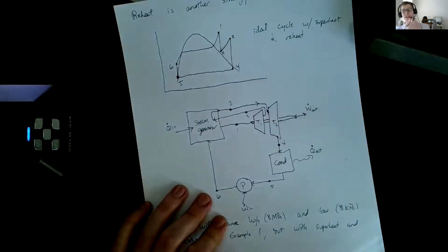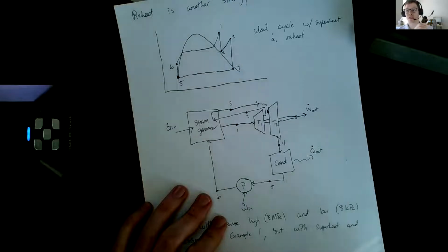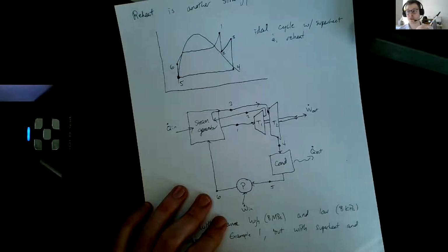There's a couple of sort of naive things that I can tell you that would explain why we have to pump out heat in the first place. One is that one of the definitions of the second law is you can't have a power cycle operating between two reservoirs where the only thing you do is take in heat and put out power. You have to have waste heat rejection, otherwise you violate the second law. So that explains why we have to have heat rejection to begin with. Number 2, another consequence of the second law is that you can't have heat flow from cold to hot.